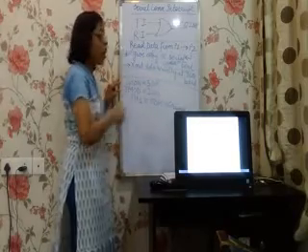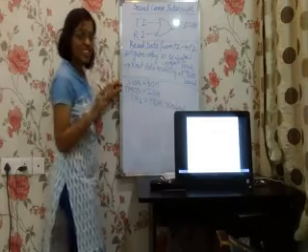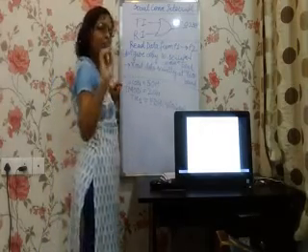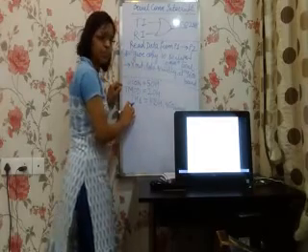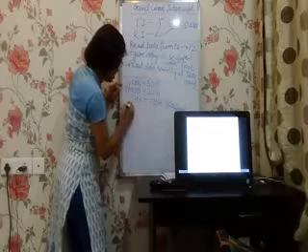Also we need to configure which register? We also need to start the timer, so we have to configure TCON. That will do only SETB TR1. Then we have to configure the most important register, that is IE.